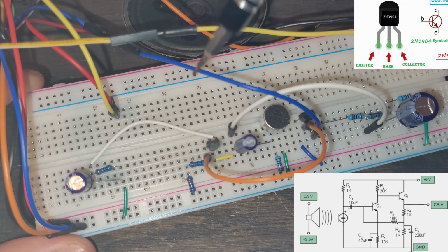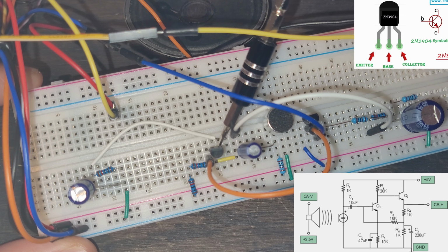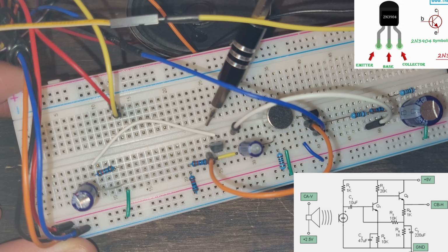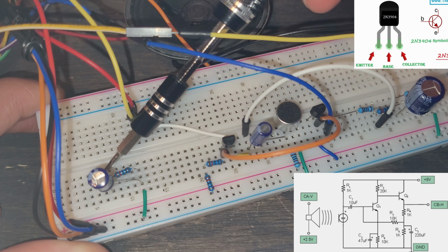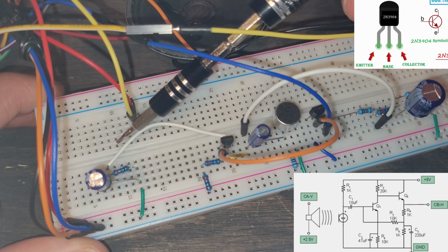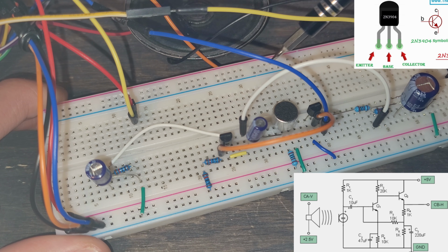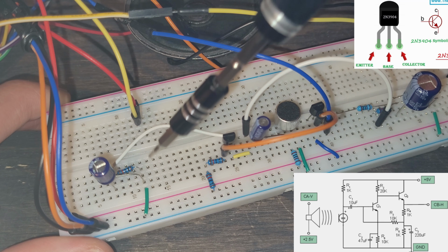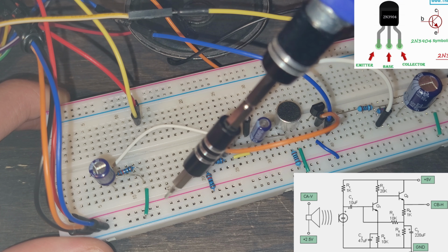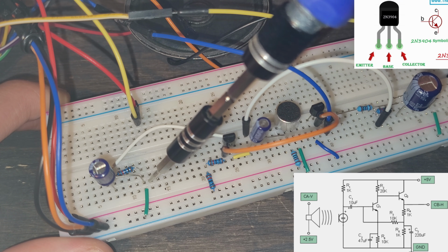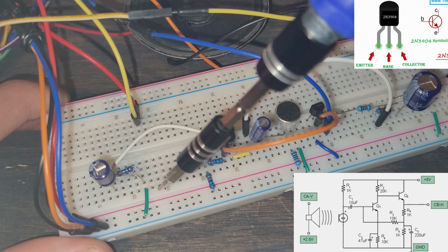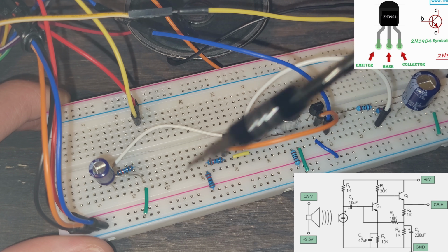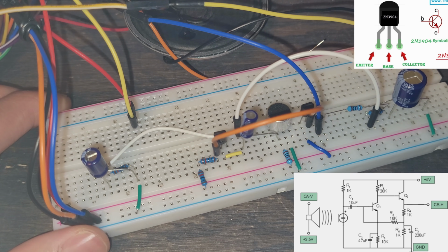So we can take this wire, this white one right here, from the emitter, which is in this row or column, and we're going to take it all the way across here, and it's going to go like this. We can see from the circuit diagram it's in parallel with this 10 kilo ohm resistor and this 47 microfarad capacitor right here. And then we have the wire that's going to take it down to ground. So the entire left side of our circuit is basically done.